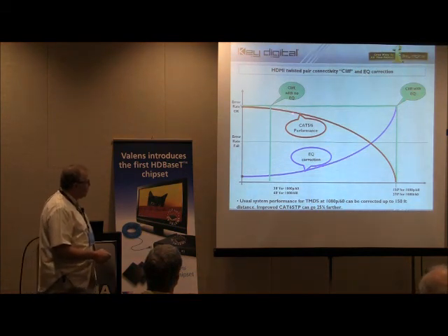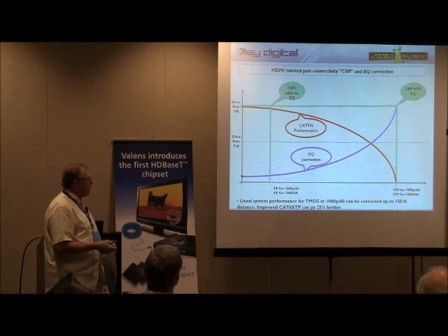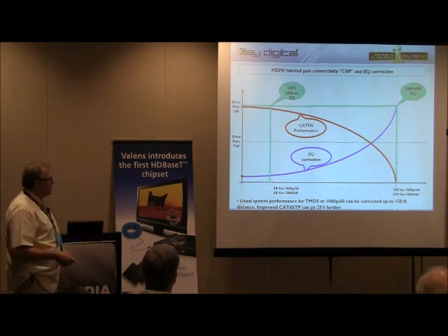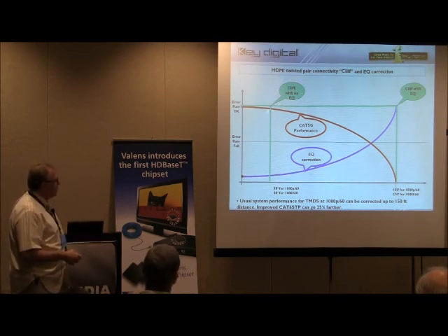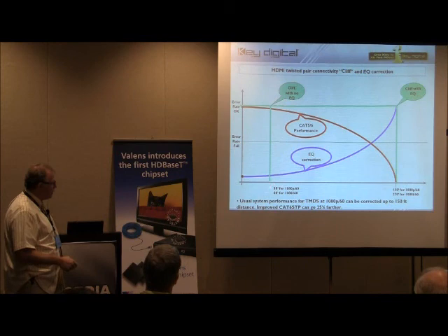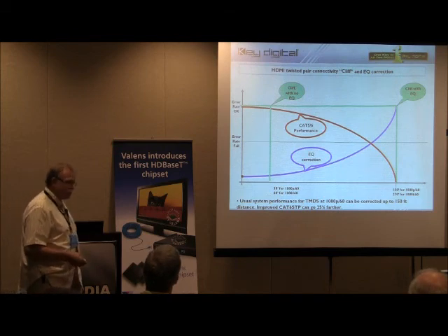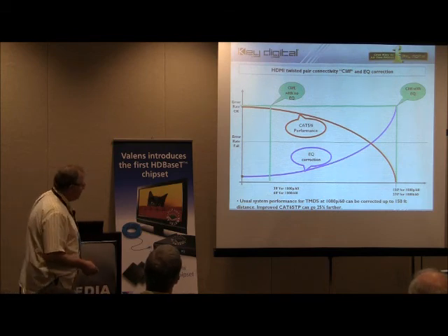If we don't have any EQ circuit, which is a passive HDMI cable, again, twisted pair that has TMDS signal on it, then the effective length of the connectivity, now there's a difference from manufacturer to manufacturer, but you can roughly say will be about 30 feet for 1080p 60 and 60 feet for 1080i 60, after which there is probably going to be a cliff effect in the majority of cases.